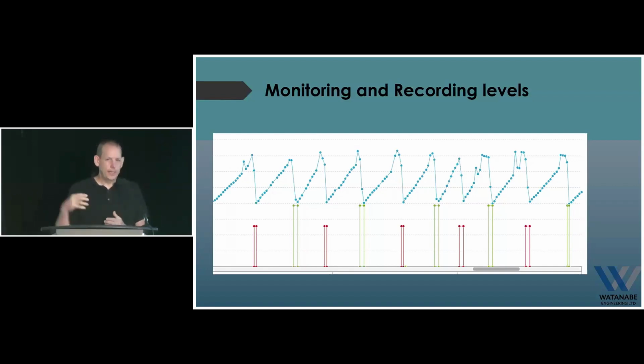But with that Ethernet, we hook it up to a radio, cellular, direct radio, whatever we need to do. Could even be Starlink. And now, sitting in Chilliwack at my desk, I can dial into the controller and get a communication path all the way through the cable to the transmitter in the wet well, and I can do an echo profile remotely.